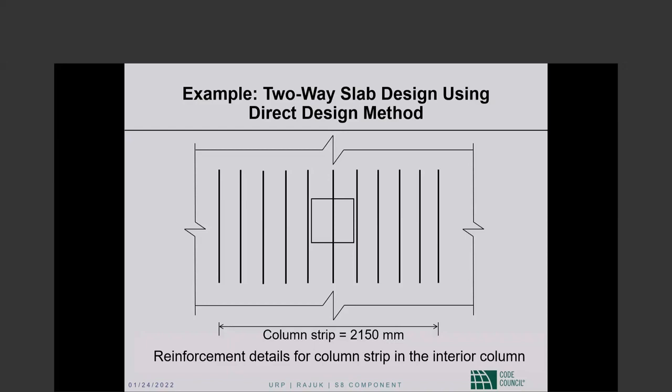But bend bars require a certain depth. I don't know that there is a code prescribed depth. I think in the case of slabs, there actually is. I forget now, 6 inches and 16 times the bar diameter, something like that. There is a provision for it. You cannot use bend bars even if you want to, unless your slab thickness is beyond a certain minimum. And I cannot remember whether it is 6 inches or 8 inches.